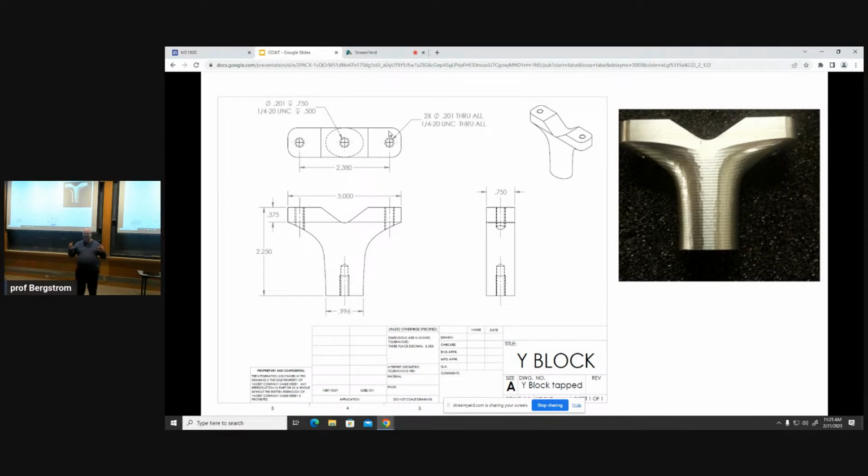The young engineer used a tolerance like plus or minus 5 on the feature they drew in, because they were used to designing machined parts. But what they needed was more like plus or minus a half an inch on location. That tolerance forced the extra step of moving to another machine to make that one hole.